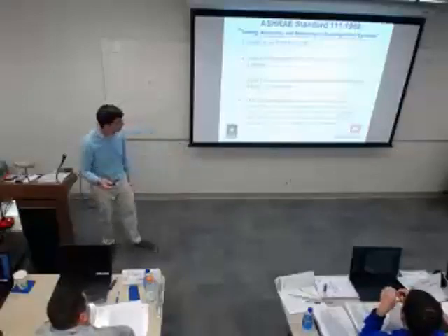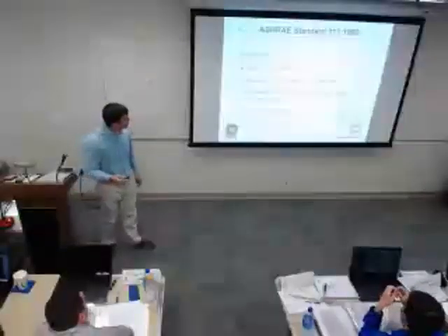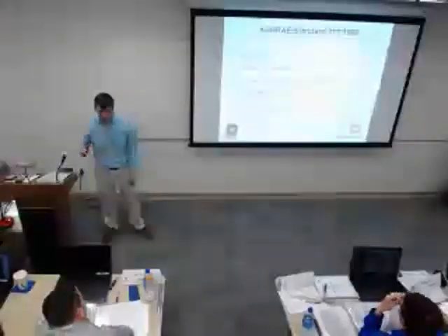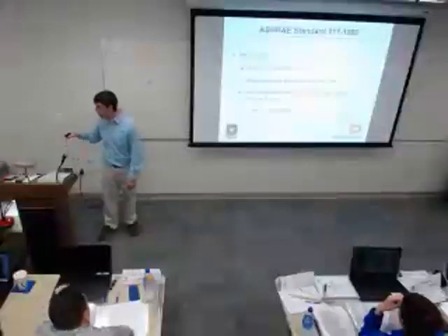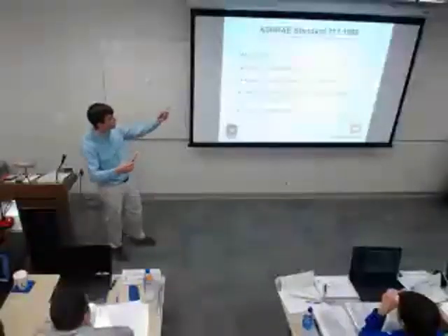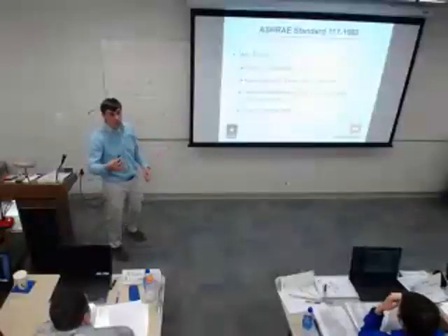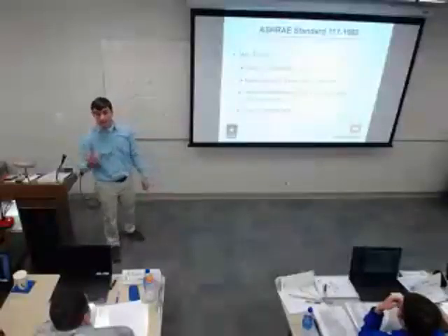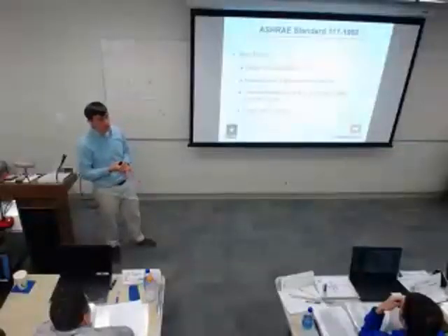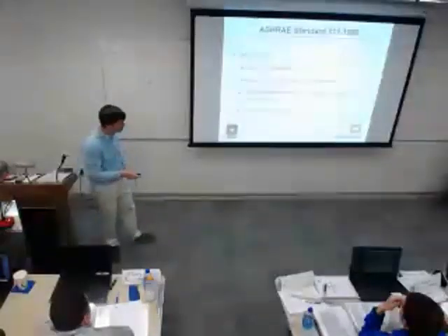Should have been up front. ASHRAE Standard 111, it is a test and balance standard given by ASHRAE. It's got a lot of the same information as those two books. I held up the actual TAB standard, so you could actually choose to use this as your TAB standard. We don't. We say go by whatever standard the TAB company we're using goes by, either AABC, NEBB, or also TABB is another one. I've never seen a TABB contractor.